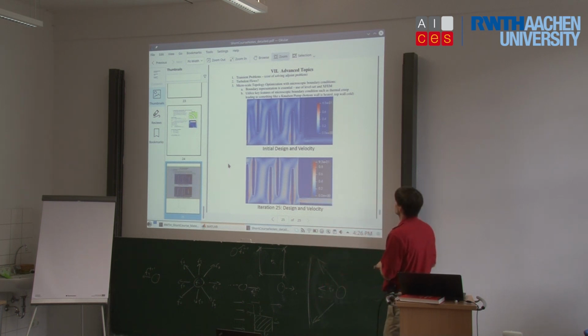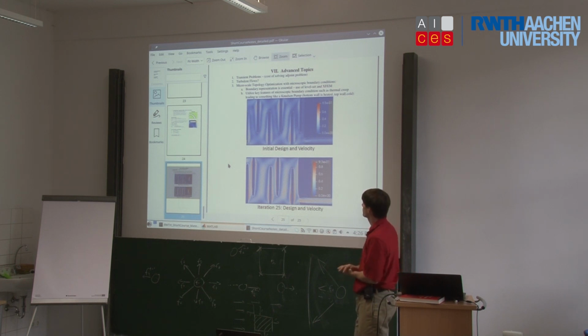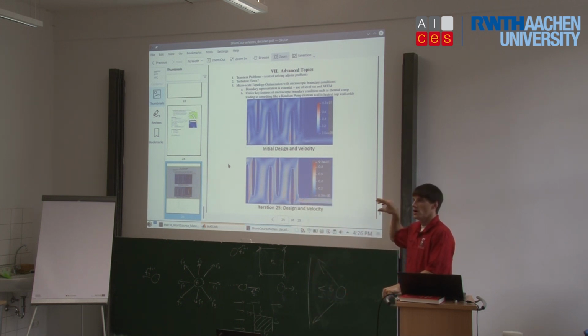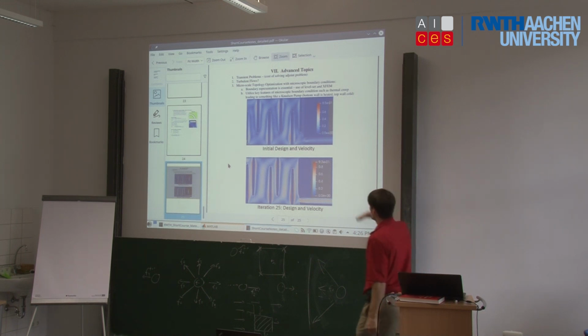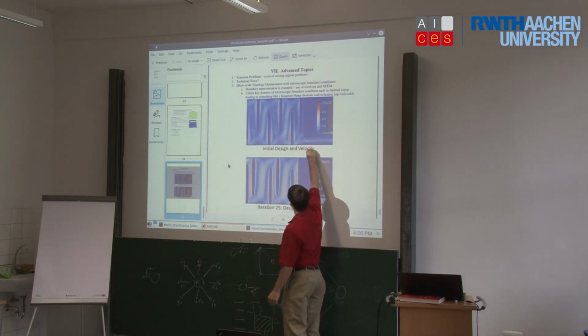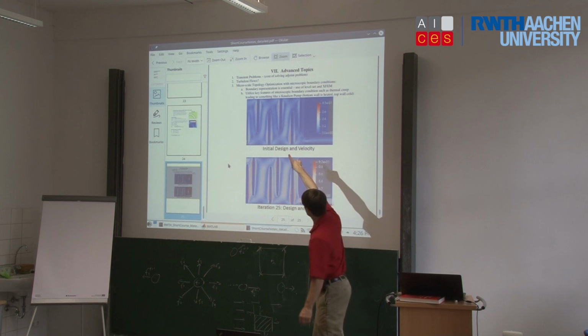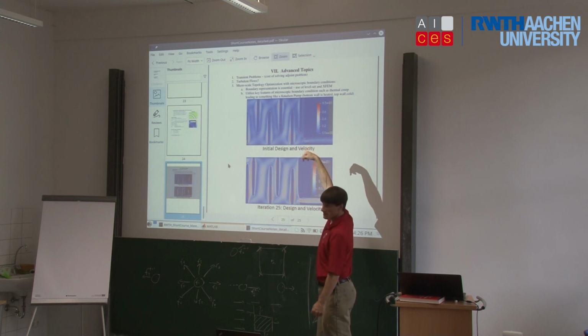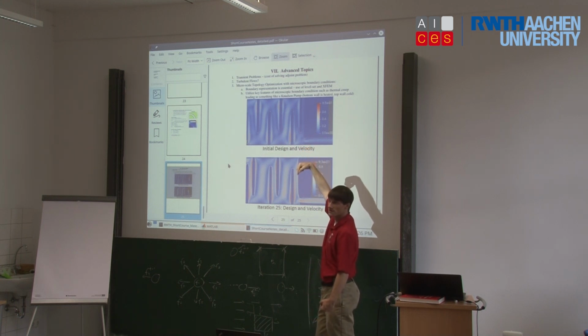Something that I'm specifically working on, that I'm collaborating on with Dr. Trillian upstairs, is microscale topology optimization with microscopic boundary conditions. So here we use level sets and XFEMs for the boundary representation. At the microscale, a temperature gradient can actually create a slip along the boundary. Okay? And so as the surface is hot, the top surface is cold, which generates a temperature gradient along these fins.